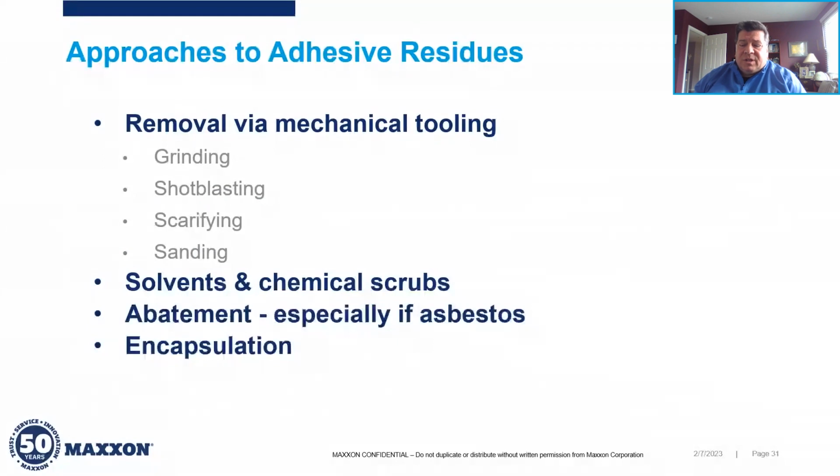So to continue that method, knowing that you're going to go through a number of these different components of the grinding or shot blasting or mechanical removal method, it could get costly, right? Because these things are going to be thrown in the garbage when they get gunked up with adhesive.